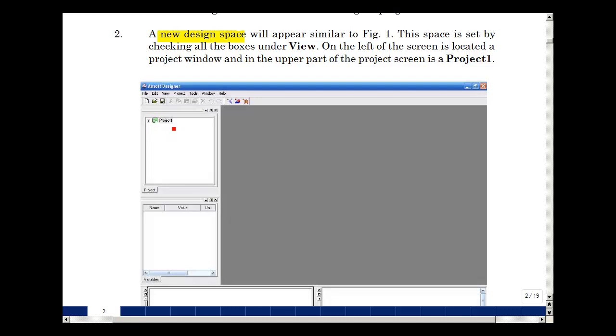Now right-click on this, and then select Insert, and then Insert Circuit Design. It's going to ask you to choose a layout technology, which is used to select a printed circuit board. We're not going to do that in this project, so just click on None. Components can now be placed under the schematic. To see the components, click on the Components tab directly under the Projects tab. And all the available RF components are listed in the project window.